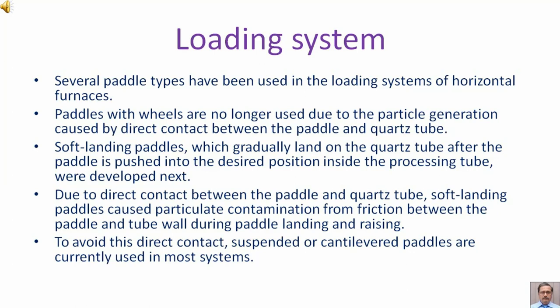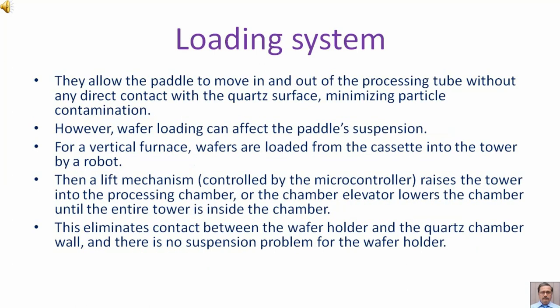To avoid this direct contact, suspended or cantilevered paddles are currently used in most systems. They allow the paddle to move in and out of the processing tube without any direct contact with the quartz surface, minimizing particle contamination. However, wafer loading can affect the paddle's suspension.